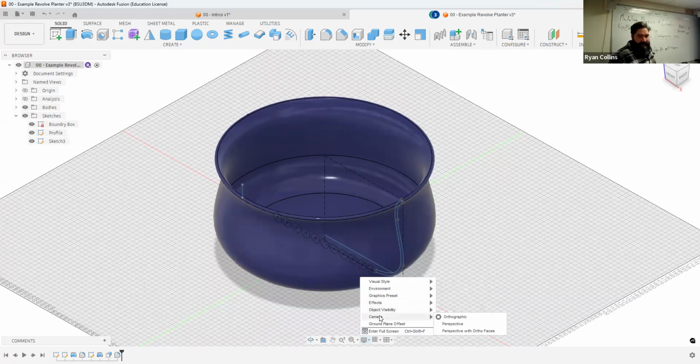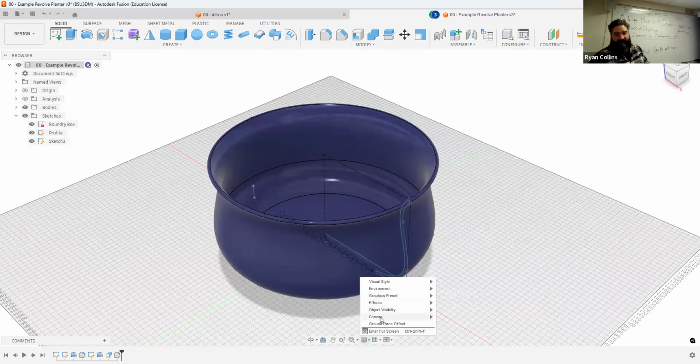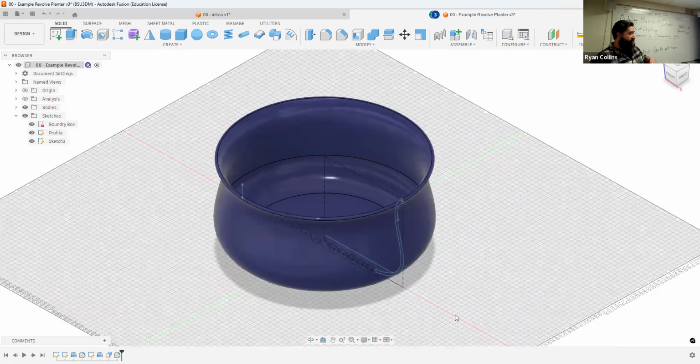Visibility is just kind of just that. Camera is just changing the orthographic view, like I said, to a perspective view, and you can see how instead of that backdrop, that virtual plane, actually being at a right angle, now it's in perspective. And because we talked about it, you'll know what I'm talking about. Leave that in orthographic view, because otherwise it just gets real awkward. Things that should align straight directly in line when you're looking at something orthographically suddenly no longer will. So leave it in orthographic view.